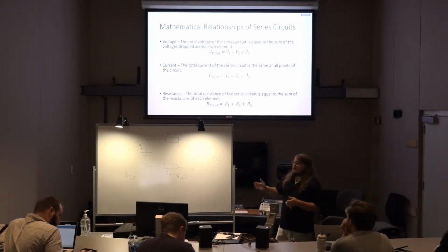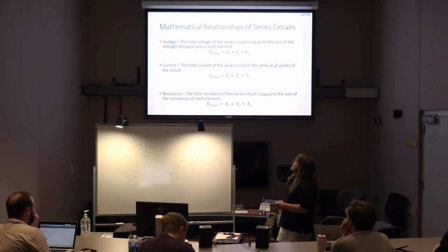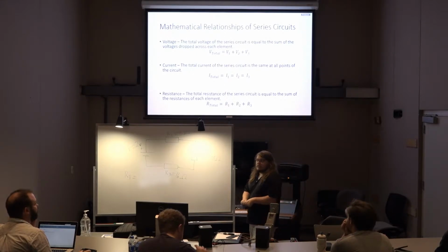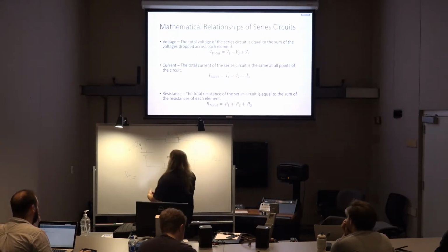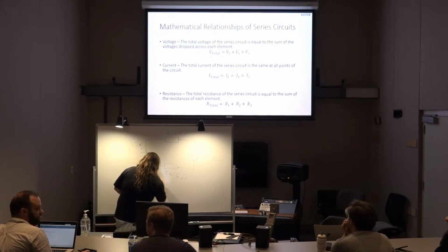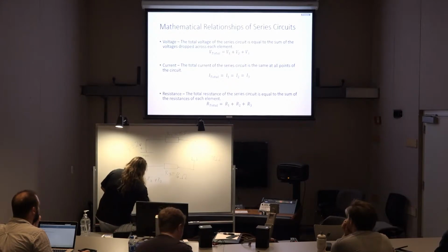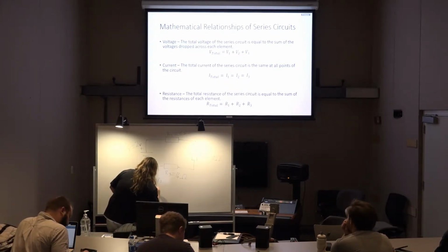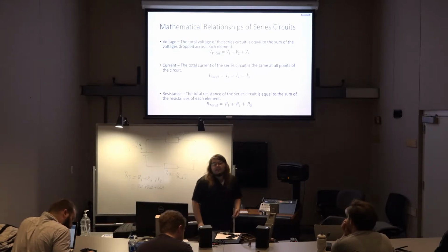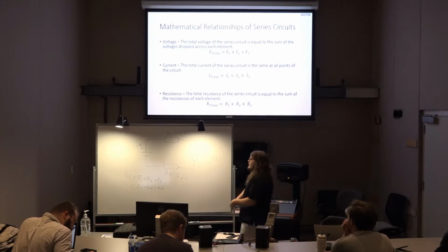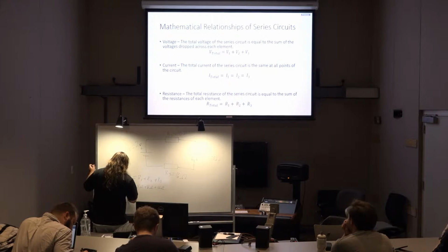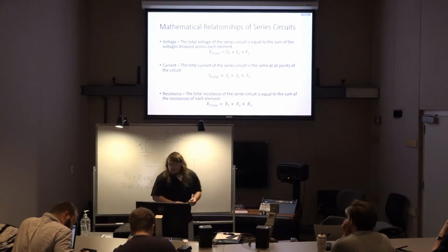So if we have RT as our unknown up there, we kind of have a handy cheat sheet. How are we going to go about finding the total resistance for this circuit? It's 8 ohms plus 8 ohms plus 16 ohms, correct? Exactly. R1 plus R2 plus R3 gives us the total resistance for the circuit, and that is, in fact, 32 ohms.